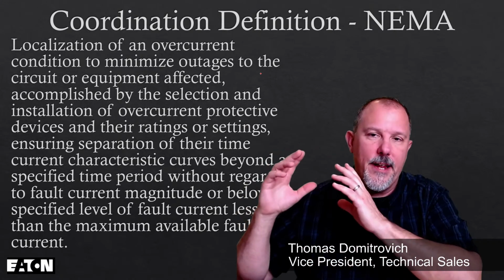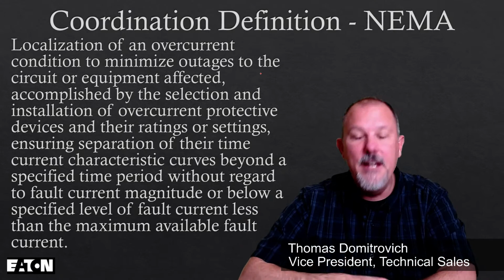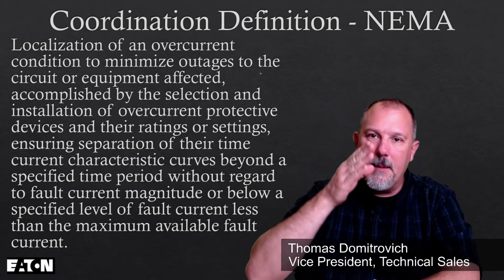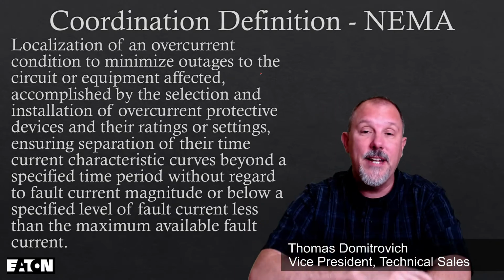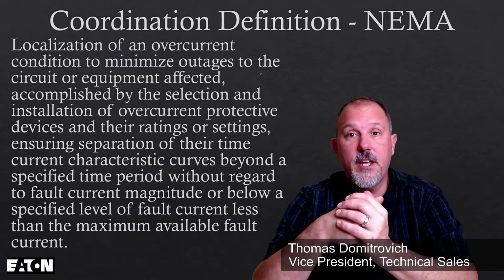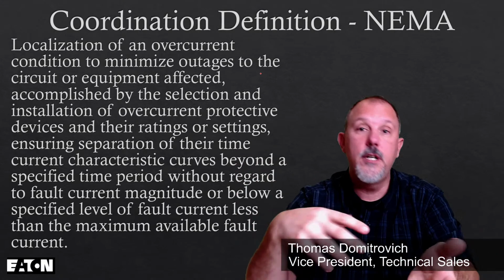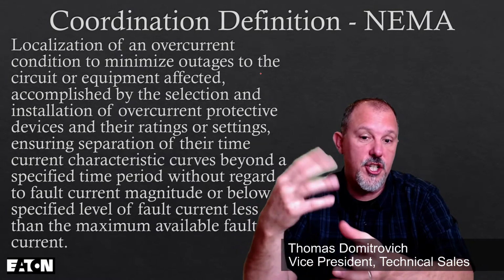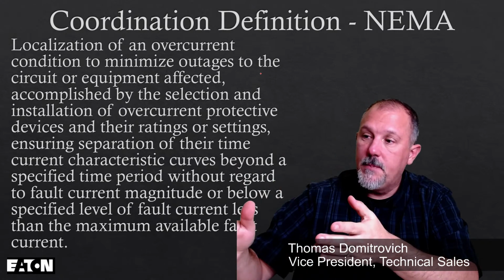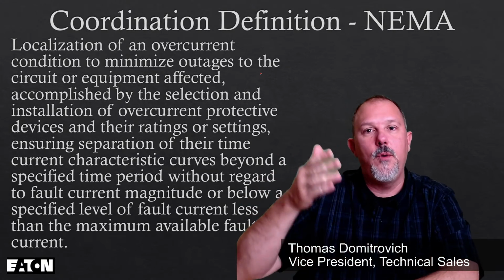reviewed, public reviewed, and peer reviewed documentation or book, and as an industry practice, the most common fault is an arcing ground fault. And oh, by the way, it's 80% of the bolted fault current value. I plotted that, and either you do or you do not coordinate to that value. If they didn't coordinate to either of them, I would then tell my customer, look, if you want a level of coordination, I would give them some options. You could make changes in your overcurrent devices, change the settings, etc. That would cover a coordination to a lesser value of fault current.